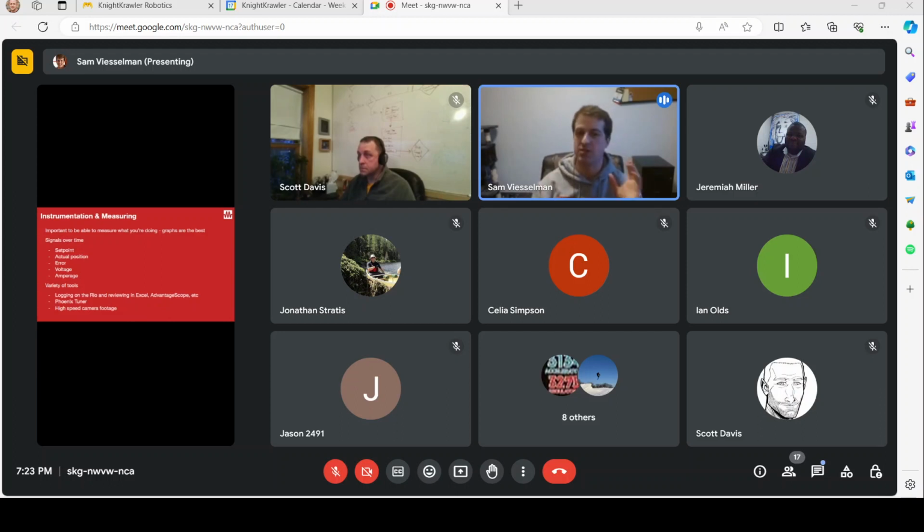And so being able to graph these signals and look at them will really help you track what the system's doing. And when you're putting in these magic constants to try to tune them in, you can actually see how they affect the system rather than trying to guess and check and having questions when there's instability. So I would say this is a really great place to start: just learning how to instrument and watch these values over time. And it should be a lot more approachable than just trying to control something right out of the gate.